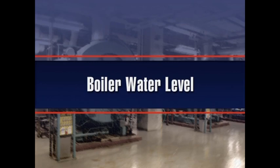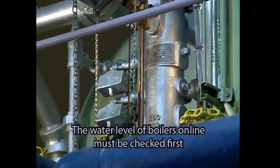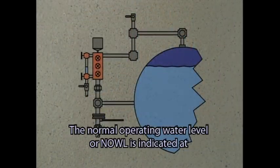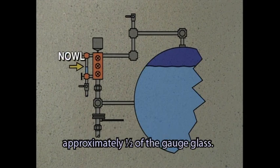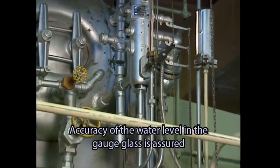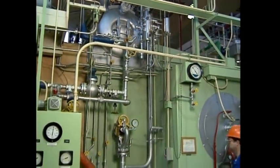Boiler water level. The water level of boilers online must be checked first by the boiler operator taking over the shift. The normal operating water level, or NOWL, is indicated at approximately 1/2 of the gauge glass. Accuracy of the water level in the gauge glass is assured by blowing down the water column and gauge glass.